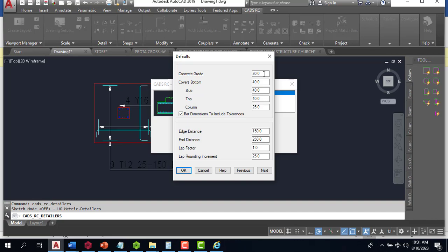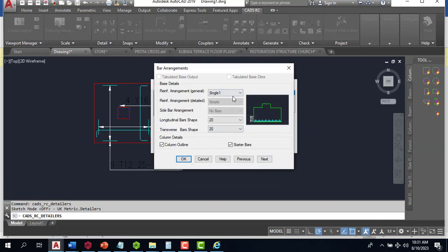In your detailing you must consider the concrete cover. So all of this information, you can just fill in based on what you are considering in your detailing, probably because of the exposure to your reinforcement, probably because of fire hazard and all of that. That will help you as the engineer to determine the right cover that you should adopt.